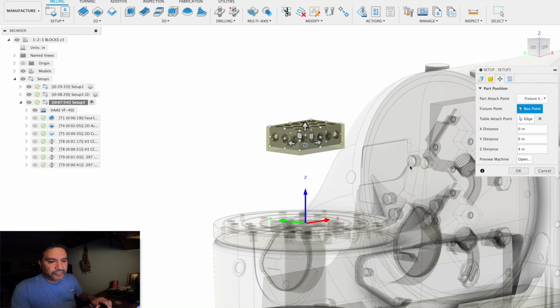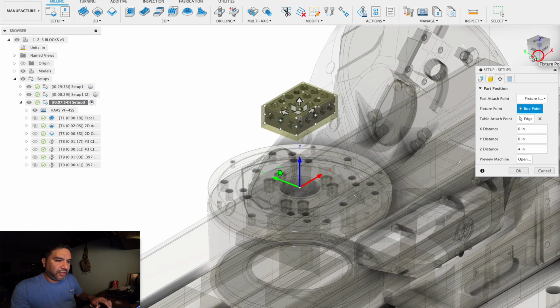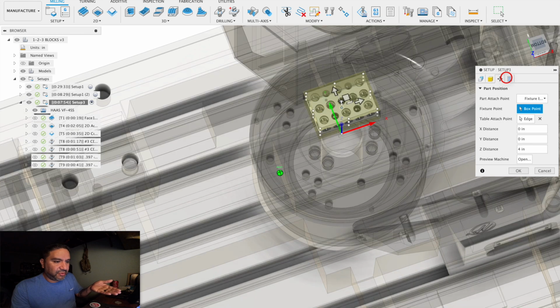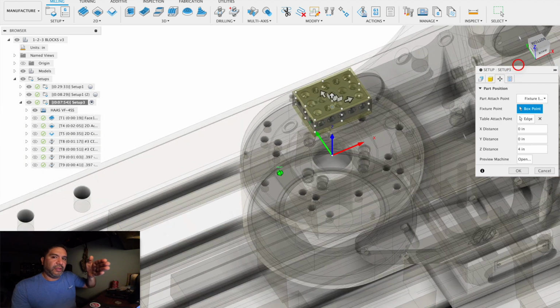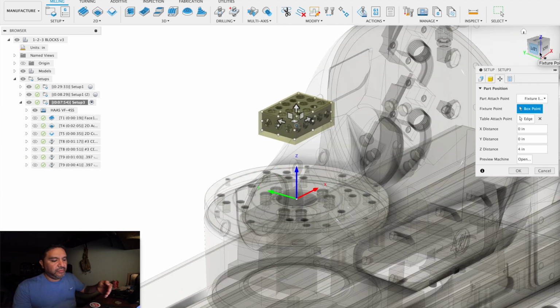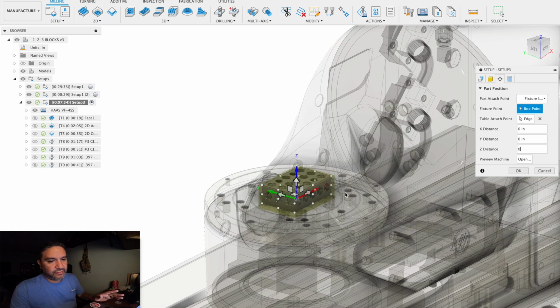If you set XY 0 from the top here, and then swing your table 90 degrees so that your part's laying down towards you, and you touch off and find what your Y axis is, that becomes the swing number. And I put that in your Z right here. It could be 0 if your part was on the table, like that. No one's doing that. It could be some odd number.